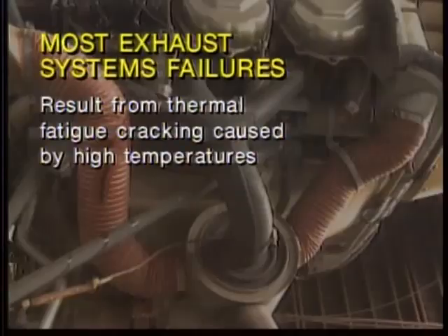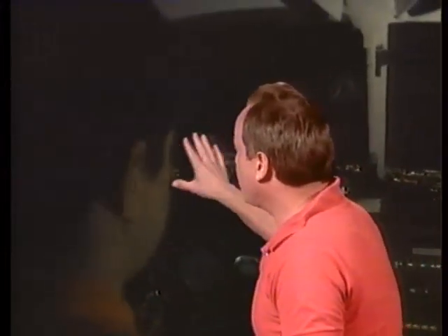And so if you're flying at night, you have this insidious thing happen to you, like the back of the head sneaks up on you, you could be having carbon monoxide poisoning. You may be not flying at night at all. Your vision just gotten very, very bad because of carbon monoxide poisoning. All right, so if you have an undetected exhaust system leak in a reciprocating powered airplane, it could lead to pilot incapacitation. It's from carbon monoxide poisoning or gas entering the cabin.